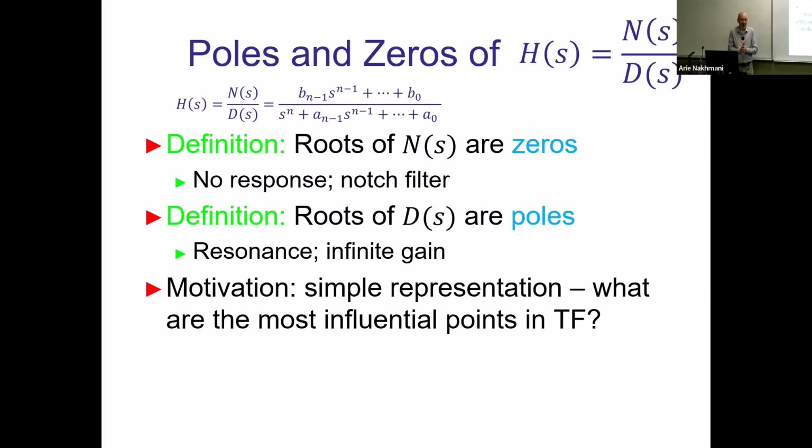So you can pass some continuous and differentiable curve between them. And this is how typically the responses look like. So you can estimate the responses just based on the zeros and poles without knowing the details of what is happening between them. And also they identify that entire thing in only one possible way. So all you need to know is DC gain, which is a coefficient of b_{n-1}. And everything else you can identify from the poles and zeros.